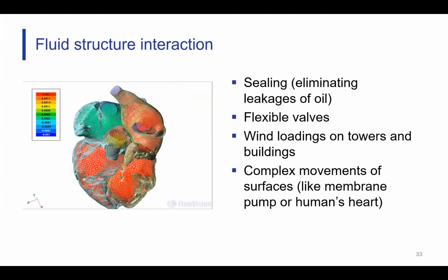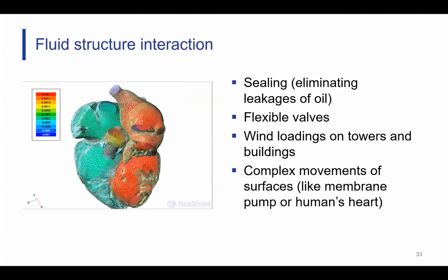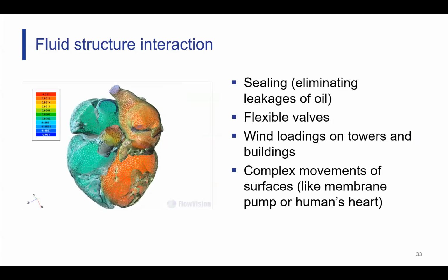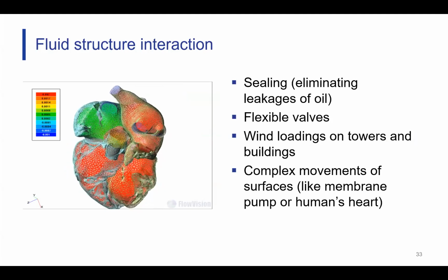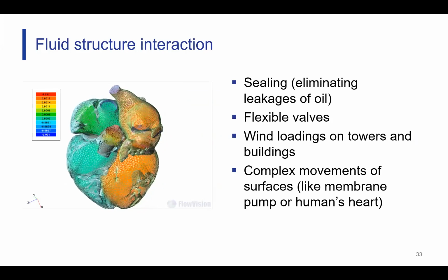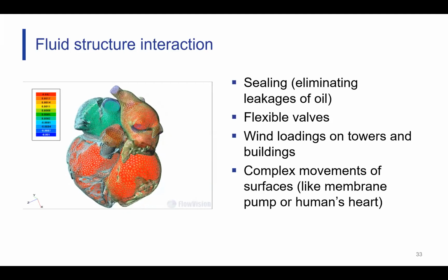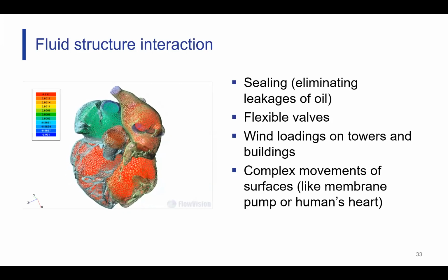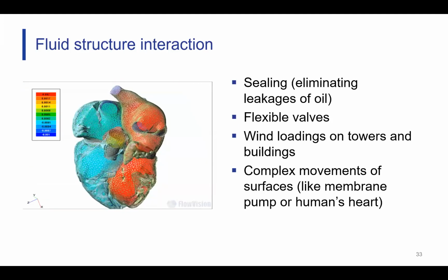Why this is important, again, let's look at this. Here we don't have anything breaking, but if you don't take this into account, you're going to overestimate the wall shear stress and kind of significantly. And this is especially key when modeling things like aneurysms. So incorrect modeling will lead to somebody getting unnecessary invasive surgery for something they don't even need. And yeah, that's not pleasant, I shouldn't imagine.